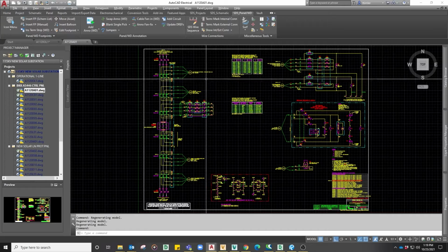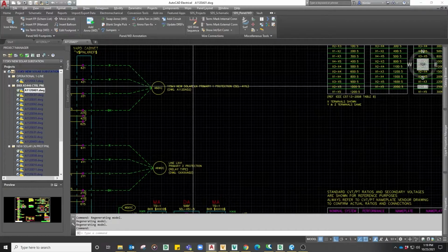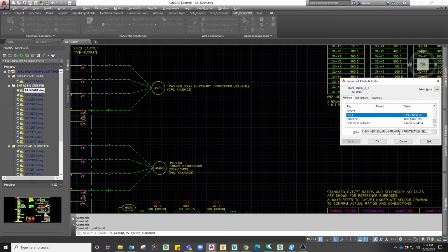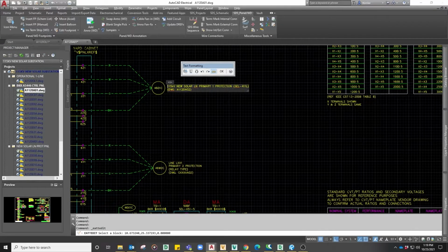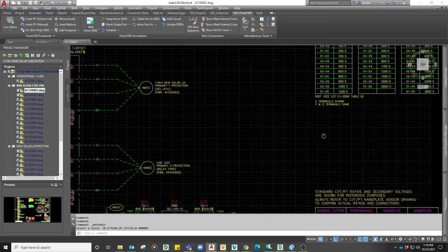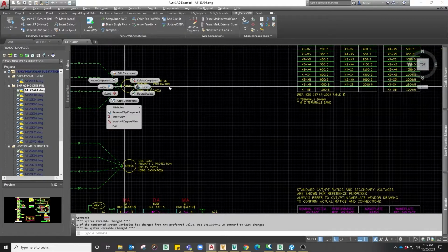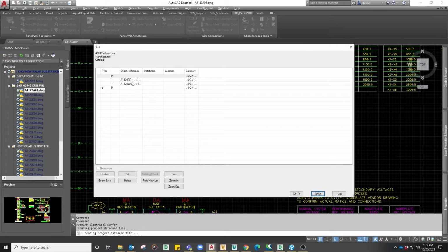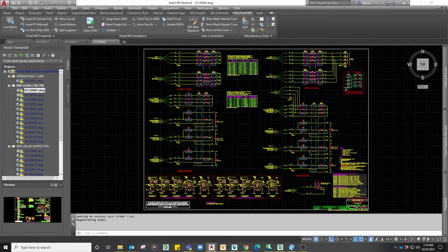Using multi-line attributes in AutoCAD Electrical causes a little bit of cleanup work because the software changes the new value to a single line attribute or a single line value in the multi-line attribute. But with just a little bit of work, you can double click on there and go ahead and rearrange the attribute text as you like and click OK. And now I can surf from this cable to the other side of the cable in the line panel to verify the same thing.